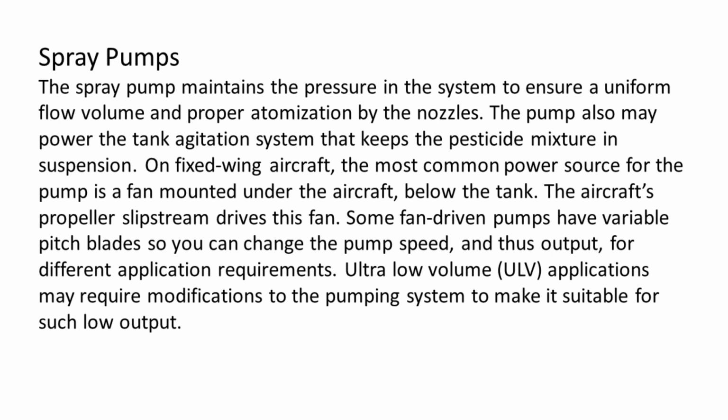Spray pumps. The spray pump maintains the pressure in the system to ensure a uniform flow volume and proper atomization by the nozzles. The pump also may power the tank agitation system that keeps the pesticide mixture in suspension. On fixed-wing aircraft, the most common power source for the pump is a fan mounted under the aircraft below the tank. The aircraft's propeller slipstream drives this fan. Some fan-driven pumps have variable pitch blades, so you can change the pump speed and thus output for different application requirements. Ultra-low volume ULV applications may require modifications to the pumping system to make it suitable for such low output.